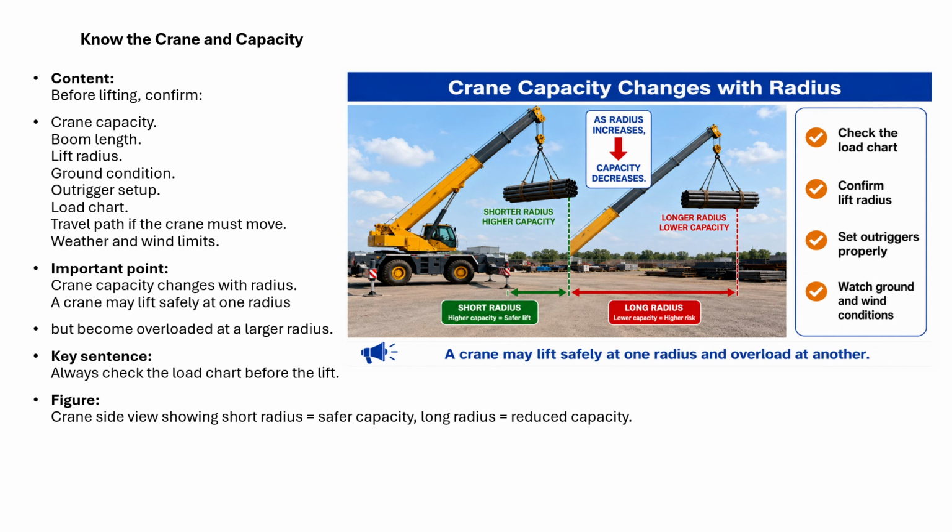Know the crane and capacity. Before lifting, confirm crane capacity, boom length, lift radius, ground conditions, outrigger setup, load chart, travel path if the crane must move, and weather and wind limits.